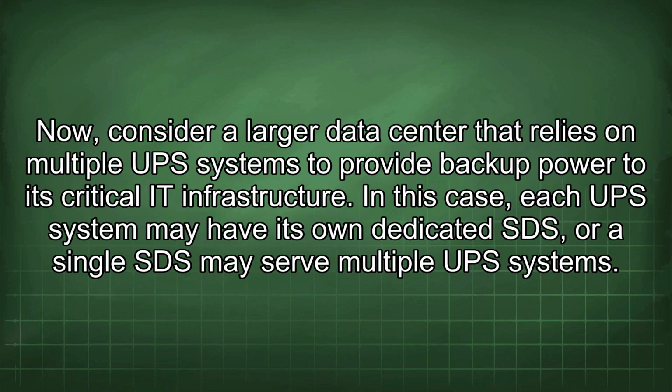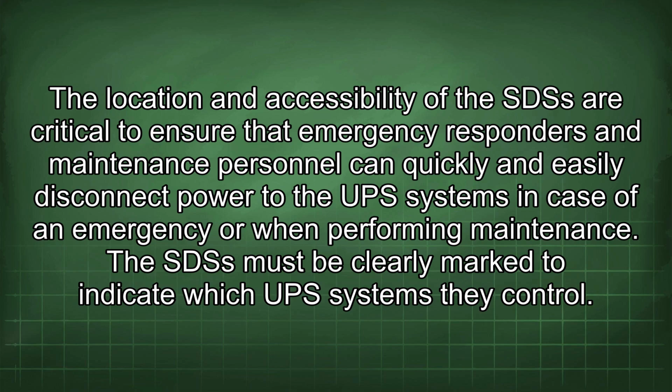Now, consider a larger data center that relies on multiple UPS systems to provide backup power to its critical IT infrastructure. In this case, each UPS system may have its own dedicated SDS, or a single SDS may serve multiple UPS systems. The location and accessibility of the SDS are critical to ensure that emergency responders and maintenance personnel can quickly and easily disconnect power to the UPS systems in case of an emergency or when performing maintenance. The SDS must be clearly marked to indicate which UPS systems they control.